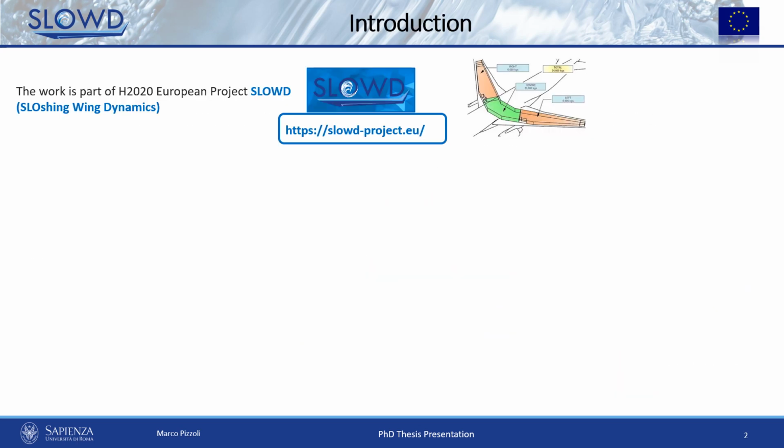As already mentioned, my PhD work was part of the European Horizon 2020 project SLOD, which stands for Sloshing Wing Dynamics. It aims to study the use of sloshing of fuel stored in wing tanks to reduce loads acting on aircraft structures. Fuel sloshing can manifest itself in many ways, but just to simplify the interpretation and understanding of this complex phenomenon, a classification based on the direction of motion imposed on the tank, which triggers sloshing, and its intensity was considered. In this way, two main types of sloshing were defined.